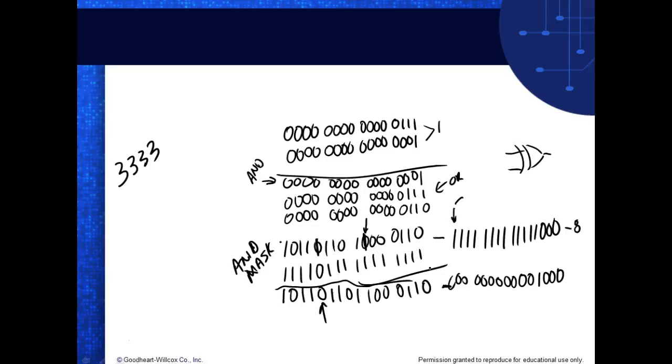So if I wanted to check to see if a bit was set or cleared, I would use all zeros, and the one I wanted to check on, I would use a 1. We'd use that as a mask. If I wanted to clear a bit or clear bits, then I can just put a 0 in my mask. You've got to understand the mask right away. And this will make sense later. I think that's covered in this chapter.